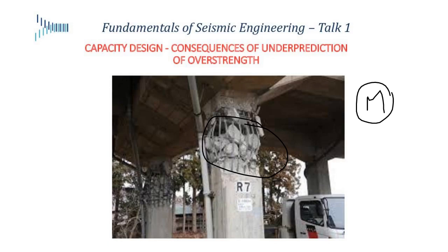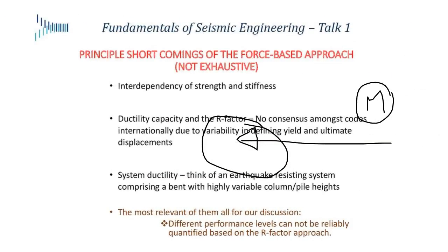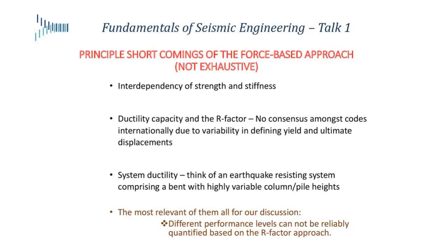It cannot behave like this, because if our fuse is not able to keep operating at that force level where it's hinged, then we're going to have structural failure. Yes, we form hinges, but we have to contain the damage and make sure that the gravity load flow and the seismic load flow keep happening through our fuse. We cannot have it just get destroyed. And that's where good detailing comes along.